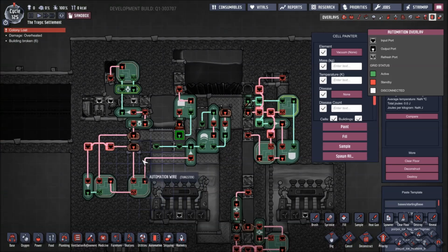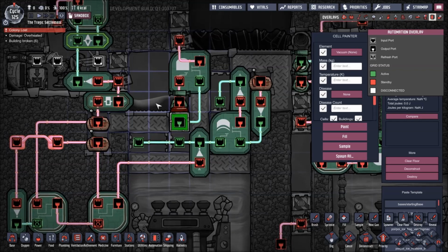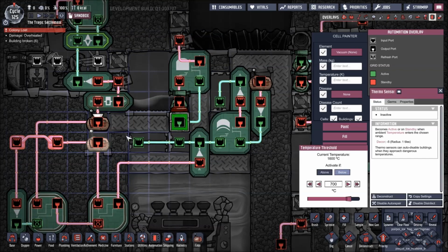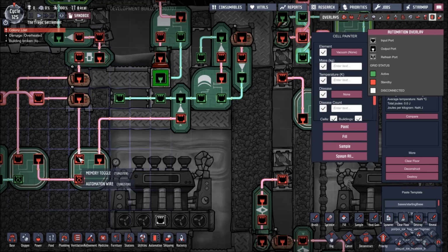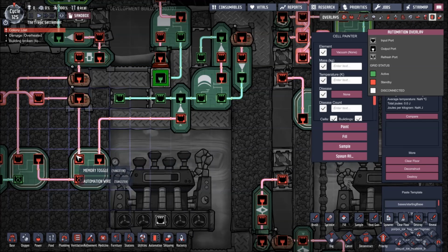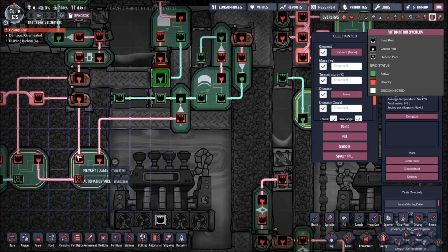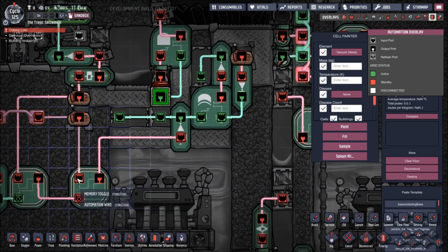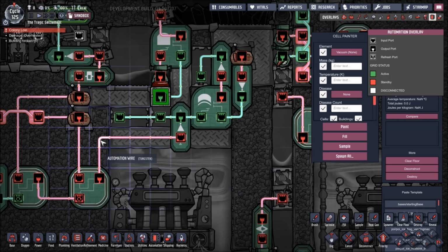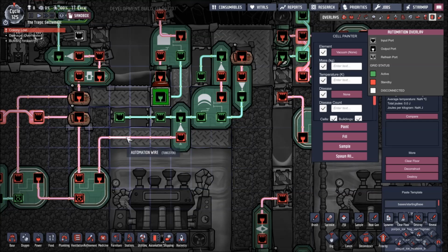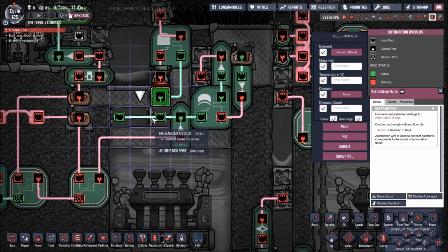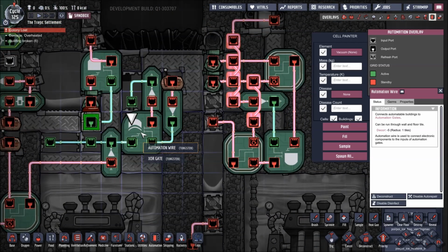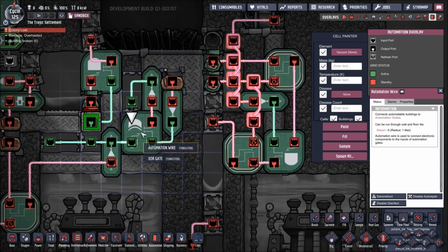So anyway, once the iron cools down to 700 degrees, this triggers closing these doors. So it goes into the active port of a memory toggle here, or it's the set port. I need to remember that. I always say active port, but it's called the set port. So it goes into the set port of the memory toggle, which triggers this to an active signal. Now that's connected to a NOT gate, so it triggers these doors to close. That also goes into one side of an XOR gate.